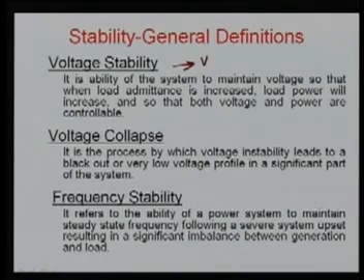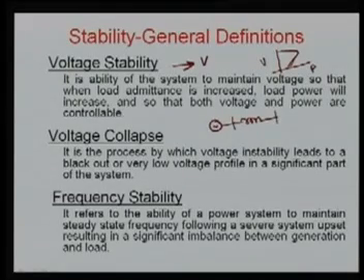What is voltage stability? To understand this, if you see the two bus system, this is your real power, this is your voltage, and if you draw the PV curve, we will come to voltage instability in detail in later lectures of this module. So, to understand it better, let us see this voltage variation. We have a system, let us suppose a generator, a transmission line, and an infinite bus, or you can say a load here. We can draw the power flowing here. If you keep on increasing the load, then the voltage at this terminal, this is your slack bus, we can draw as per this characteristic.